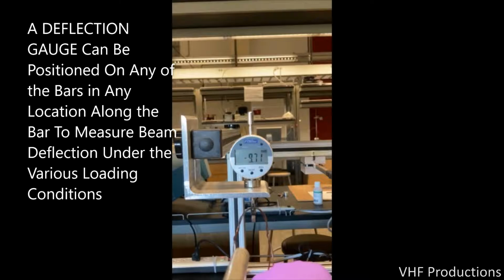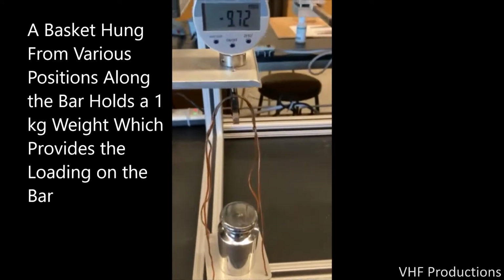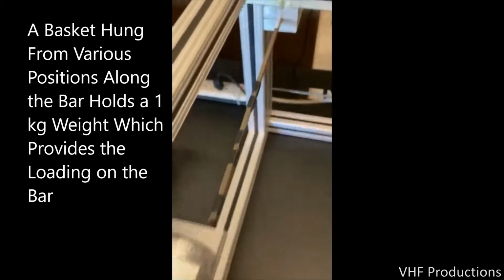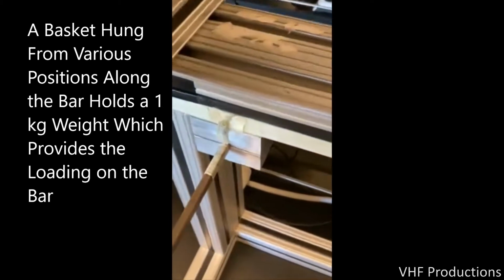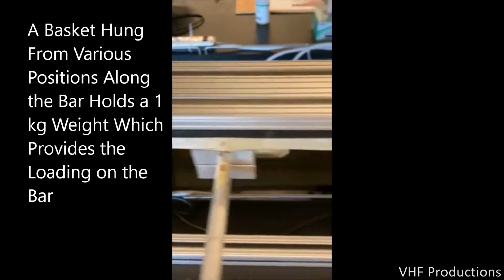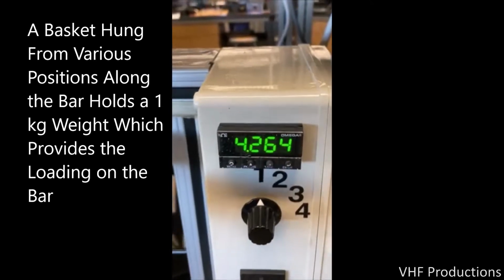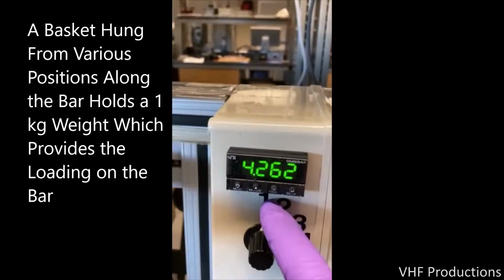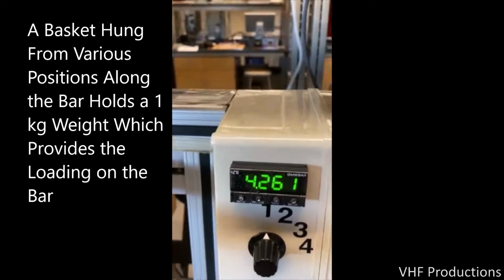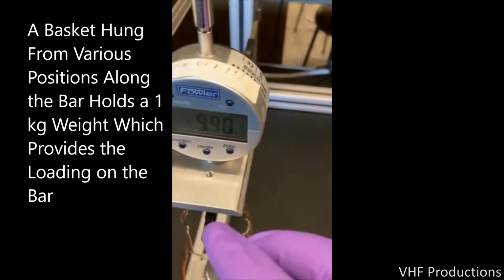Now we will apply the weight to the basket, and that weight will load the beam and make the beam deflect. And we will measure the deflection distance. Using this deflection gauge for each experiment, we're going to measure the deflection with 1 kilogram of load at each of the 4 positions along the beam length and for each of the 4 beams. We will make a total of 16 different deflection measurements using the 1 kilogram load.